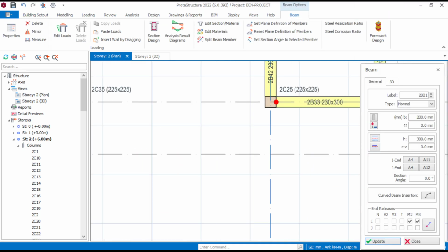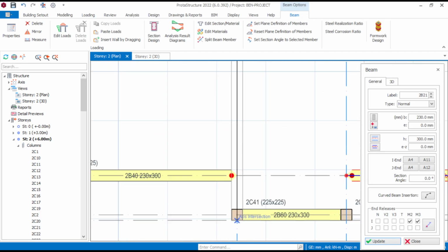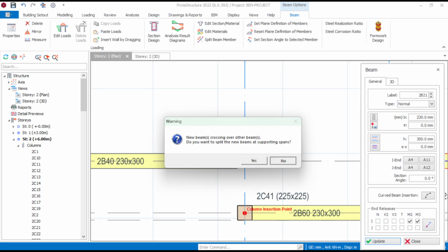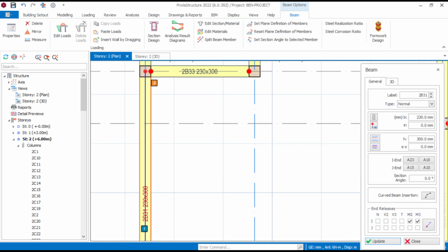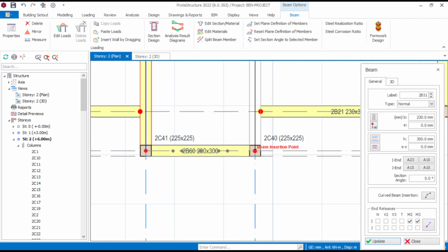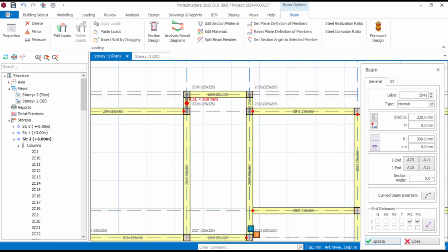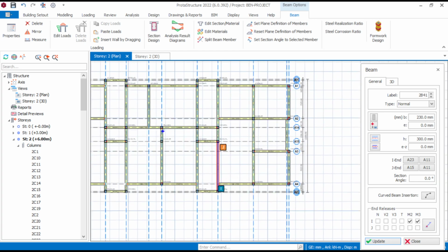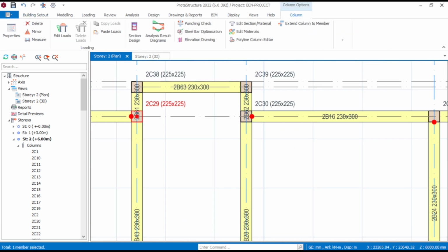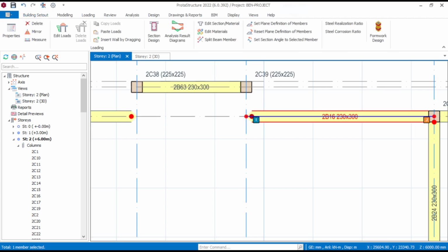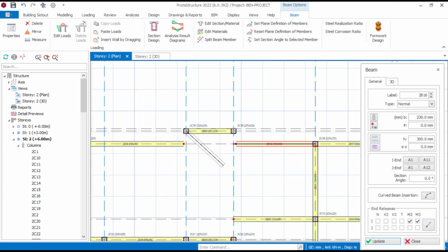Those columns are actually there because of the roof. Because the roof is definitely going to project out here, so we need a column outside there to actually support the roof out here. Are we together, please? Yes. So these columns are actually going to terminate at the first floor. So the same thing here. Let's delete this column. Let's go to properties.